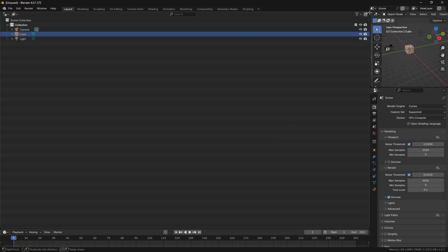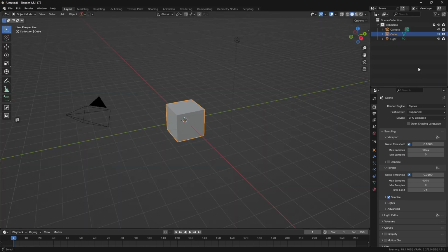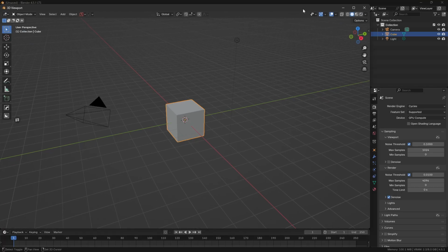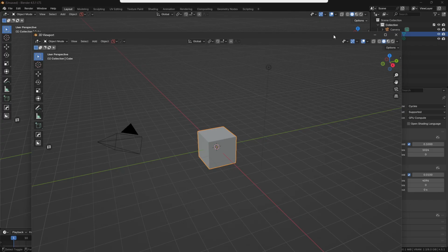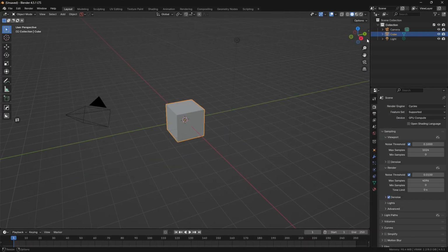If you are lucky enough to have a second monitor, Blender has you covered. You don't want your main UI stretched across 2 screens. Instead, hold Shift and drag a window corner. This pops the editor out into a completely floating window. You can drag this to your second monitor. I love using this to keep my shader nodes or reference images on a separate screen while I model on the main one.